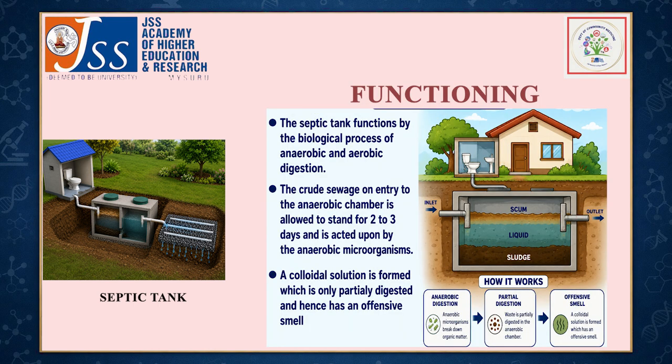Functioning. The septic tank functions by the biological process of anaerobic and aerobic digestion. The crude sewage on entry to the anaerobic chamber is allowed to stand for 2 to 3 days and is acted upon by the anaerobic microorganisms. A colloidal solution is formed which is only partially digested and hence has an offensive smell.